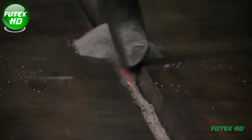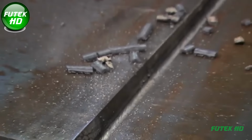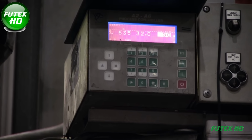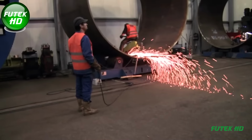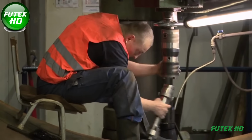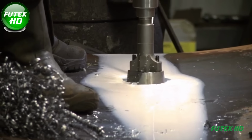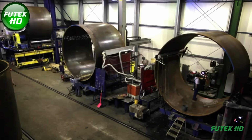The integrity of each weld is verified through multiple inspections, which include visual checks and advanced magnetic testing. Once welded, the seam is ground smooth, and 4 injection holes are drilled into each pipe. These holes serve a critical purpose during installation, allowing concrete to be injected between the pipe and the surrounding rock to provide additional support and stability.